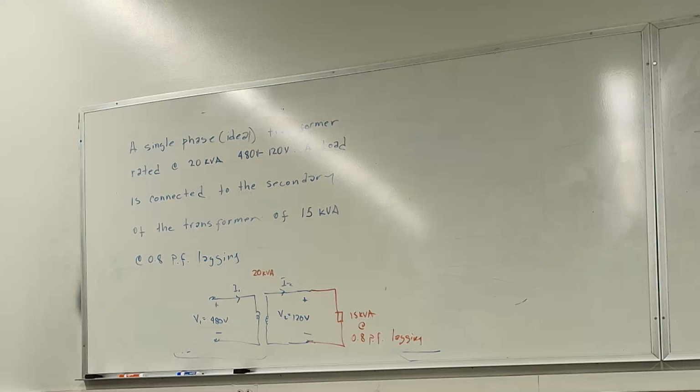Transformers have been designed, obviously, to run below their rated value. And like in the summers, when they actually get an overloading of the transformer, they've been designed so that during the day you can be pulling more power, more current, out of the transformer, but you're hoping that at night the transformer is going to cool off. It's a question of heat, right? Because if you're pulling more current, you're basically eating the life of the transformer. I would say eating the life, not damaging it.